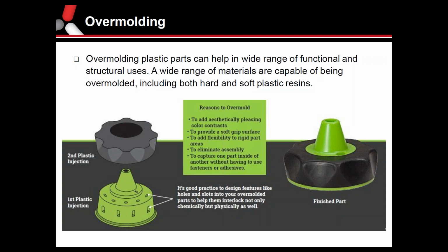And with that, you have to keep in mind for your design and materials, chemical bonds and mechanical bonds or mechanical holds within that. So kind of in the bottom left corner there, we have those little windows within the part. And what those are for is the material to kind of flow through and lock into the part so it doesn't peel off or fall off in use.